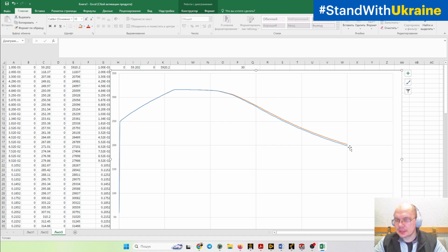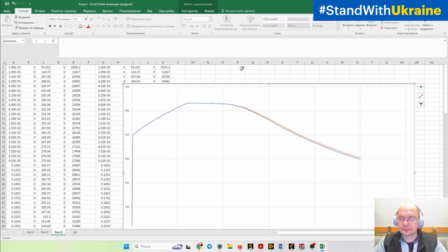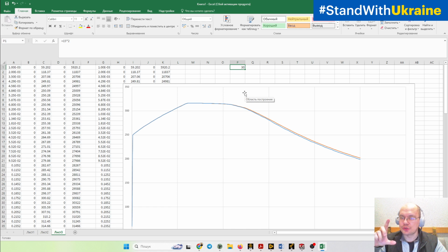We obtain this type of behavior because at the end of our tension, the thinnest part has only 30% of the area compared to the previous 100 square millimeters. So these numbers should be multiplied 3 times, 1, 2, 3, to obtain the real stresses and the real graph.